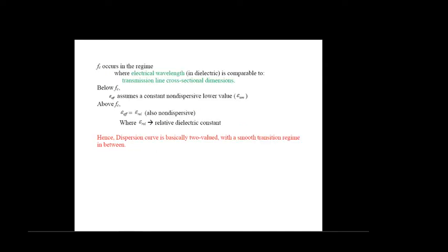The critical frequency occurs in the regime where the electrical wavelength in the dielectric is of physical dimensions comparable to the transmission line cross-sectional dimensions.